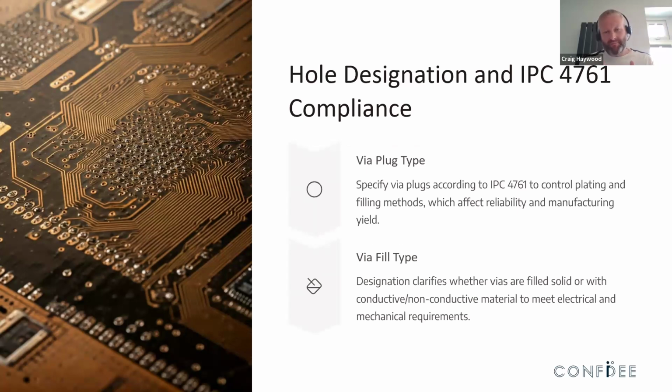Via plugging, again, important to follow IPC 4761 standards. Different variations, whether it be a via plug ink, whether it be plugged from one side, whether it's plugged from both sides, you will know, or should hopefully know, what is best for your assembly process.